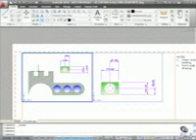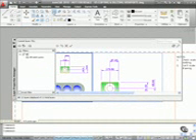So I'll freeze the dimensions 10 in the current viewport there, close the layer properties manager, and you'll see that they've disappeared like that. Now they're not the ones that I want to get rid of. I want to leave the red ones there. So if I just do that again and go back, dimensions 5 are the ones that I want to get rid of in the current viewport.